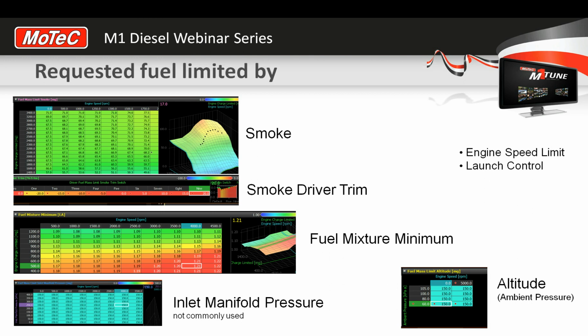Again, I know too much use of the word lambda in that sentence, but you can target different numbers here. Just because they're not the same as what the lambda sensor is actually measuring doesn't mean you have to use those numbers. So sometimes these numbers can look a little funny and unusual because your fuel injector calibrations aren't right.